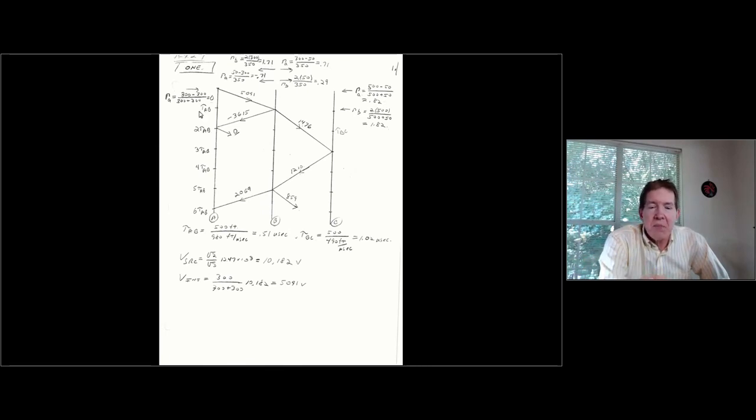And what's interesting is, if I have a waveform going back toward the source with that pre-insertion resistor there, the reflection coefficient at the source is (300 minus 300) over (300 plus 300), which equals 0. So another nice thing about matching the impedance of the pre-insertion resistance with the surge impedance of the overhead line is that I don't get any contribution back from the source once the switch is closed. So anyway, this is the diagram.